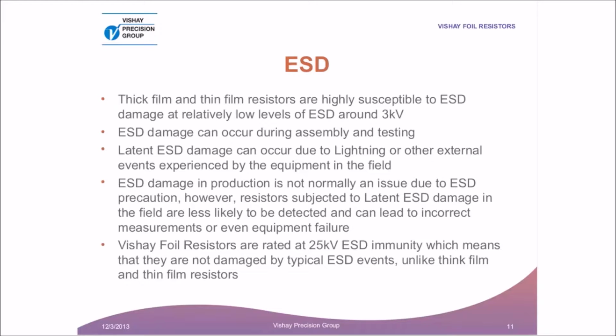Again, just to add, this is an unseen danger. Thin film resistors can actually be damaged during manufacturing and appear to function okay, only to prematurely fail after installation and a relatively short use. It's an insidious danger. We actually have a video that is very, very good about this. It's on our website, and it points out and shows how easily it is to damage a thin film resistor, shows the actual damage, and gives an indication of what can actually happen down the road to that particular part.